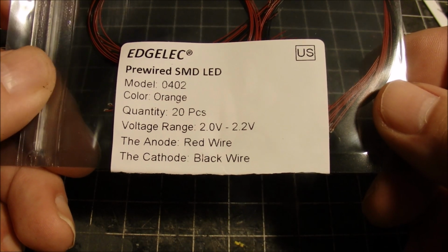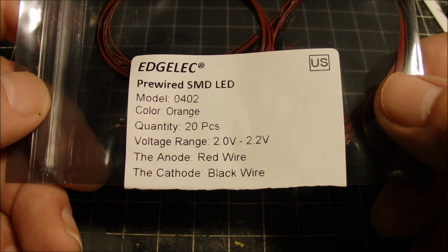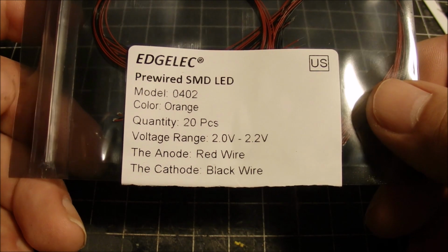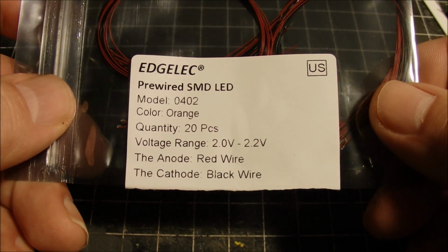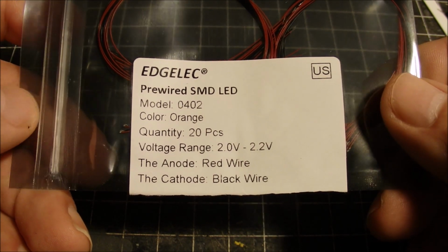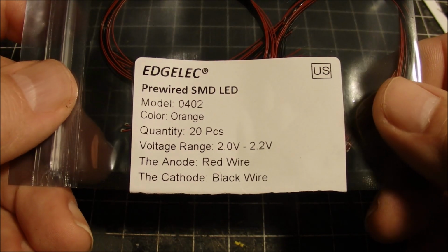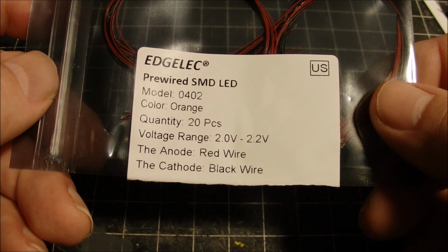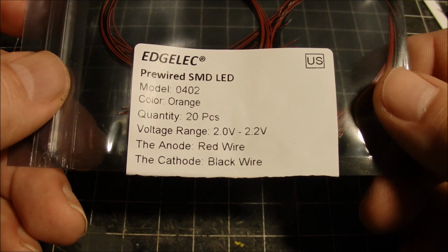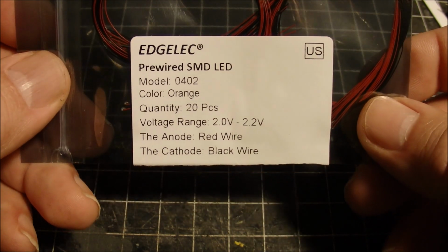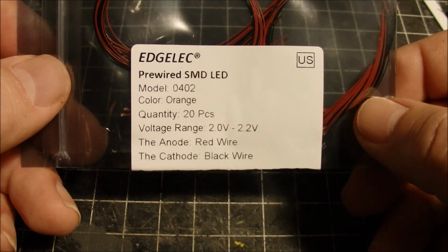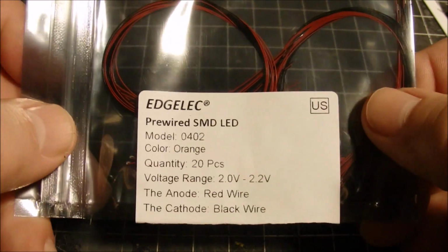I think I used 220 ohm resistors for pretty much all of them, except for the green lights. The green lights tend to be a little bright, so you might want to use a little stronger resistance there. And the blue light that I had turned out to be kind of dim, so I used less resistance on that one to try to equalize the brightness of the lights. So do a little experimenting to get the look you want.